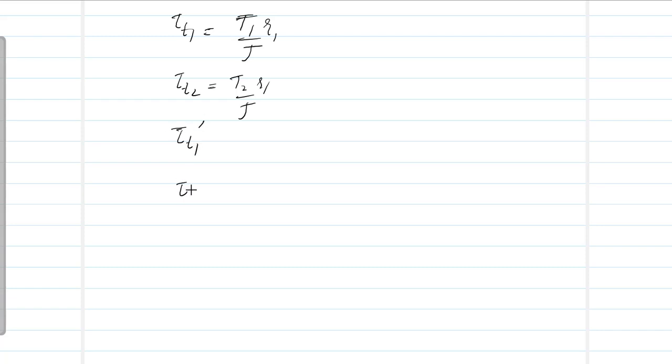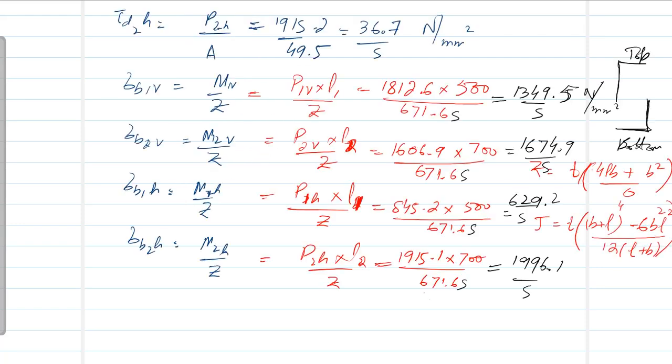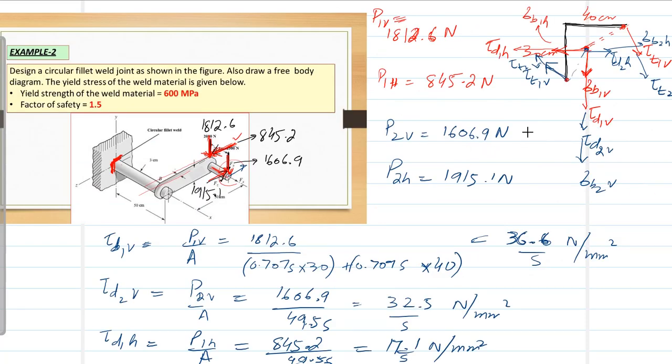This is the slight difficulty in those problems because we have two free ends and stress concentration is on both free ends, and because R is different for both edges from the centroid, we have to find four torsional shear. Before that, I was saying in the lecture that you have to find two torsional shear. Yes, that is for the one point, but because R is different for both points, the distance from centroid to the two points is different. We have to find two torsional shear stresses for two different points.